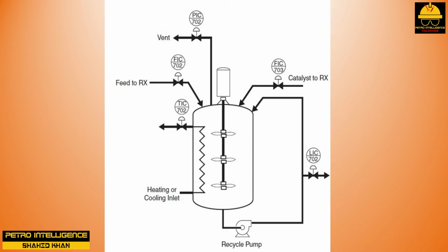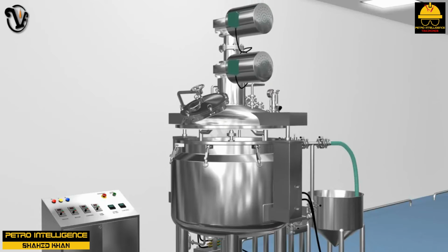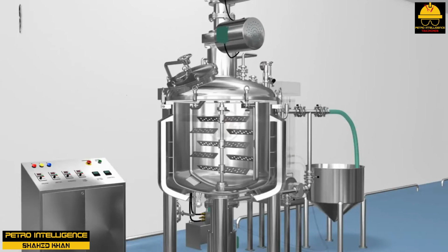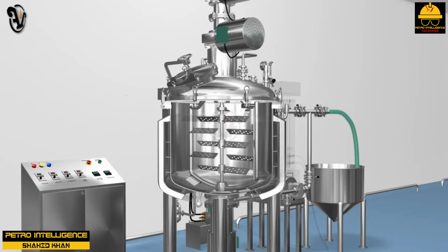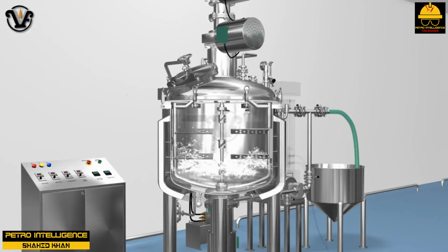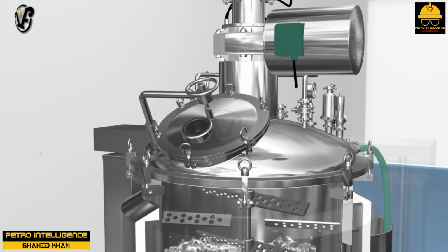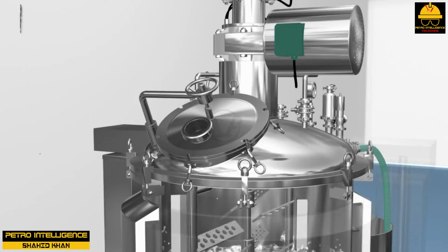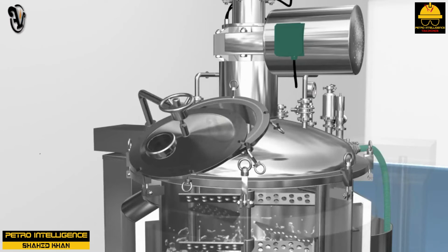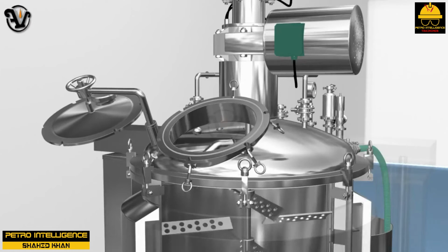The automatic shutdown allows a technician to push one button and shut the unit down in the event of an emergency or runaway reaction. A stirred tank reactor is often referred to as an autoclave or batch reactor. This type of reactor is used in both batch processes, such as the suspension vinyl resins unit and the phenolic resins unit, and continuous feed processes, such as the solvent vinyl resins unit and the polyethylene unit. The basic features of a stirred reactor are designed to provide long reaction times, mechanical agitation, and a method of cooling or heating the reaction.